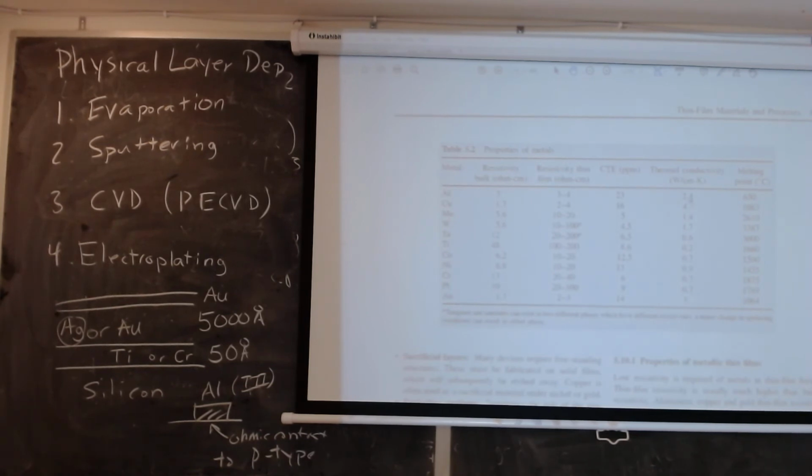And this is a useful thing to know too, the thermal conductivity. Sometimes when you're making devices, you not only want to use the metal contacts as an electrical contact, but as a thermal via. What this shows is that it doesn't have silver. It's listing copper as 4 watts per centimeter. That's a little bit on the high side. For some reason, silver is not listed.